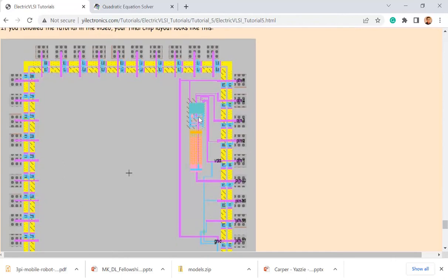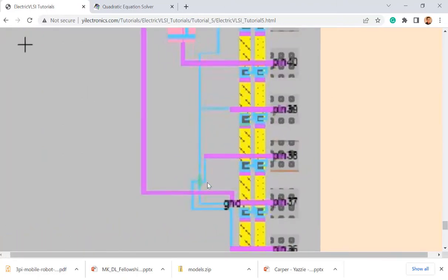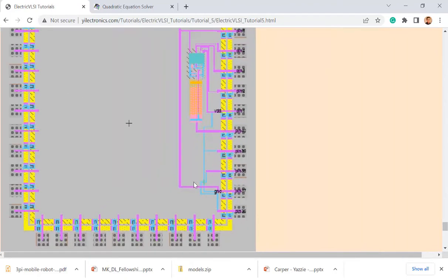Right. And then what? If you look at the, I don't have a gate. I think this little guy is probably a ring oscillator or the inverter. And these ones are the ESD diodes. What's the name of ESD? Electrostatic protection diodes, right? So when you touch it, it's going to discharge it to clamp it at VDD or 0, right? Or minus 0.7 volts.